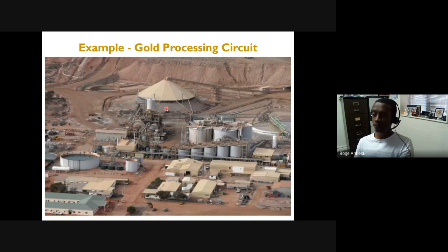The coarse ones usually fall to the ground and aggregate somewhere here, while the fine ones are aggregated to the top. Usually what happens naturally is your target, your valuable mineral, goes to either the fines or the coarse, and usually goes to the fines. So whatever sampling you do should take into account the differences in properties of the material, and should be able to capture whatever is coming to the stockpile.